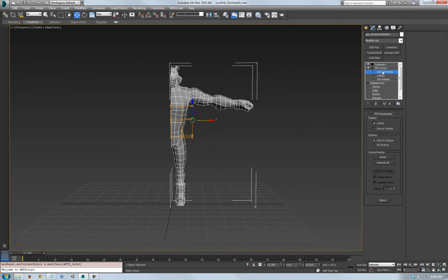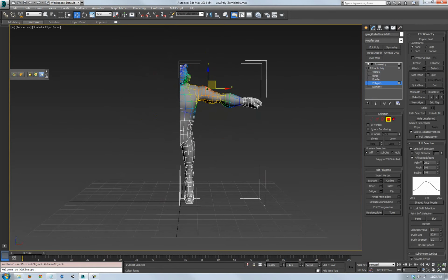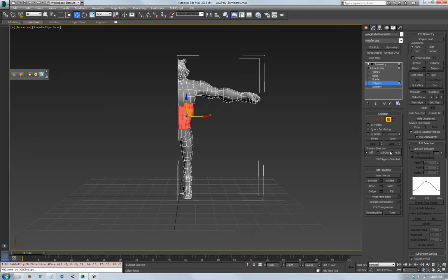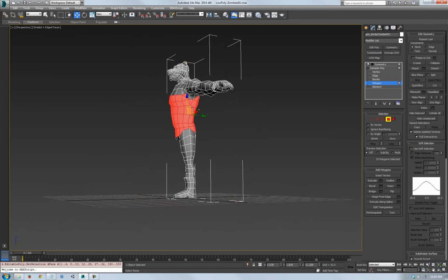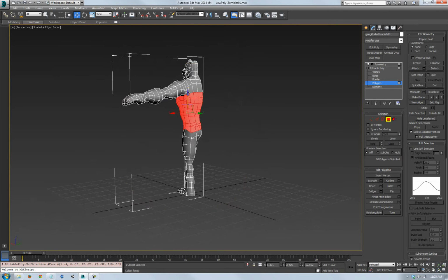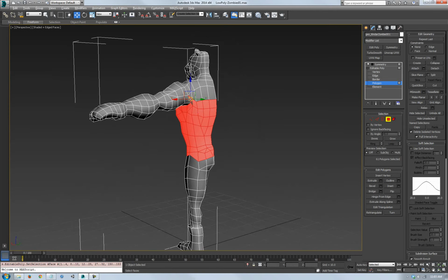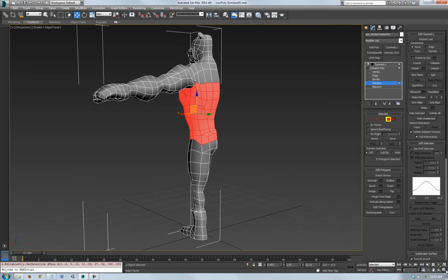Alright, so say that I've got this volume here, and when I go into the control points to modify it, as you can see, when I move this around, it's also moving the rest of the mesh around. So this does have a lot of potential power in it, but it also has its limitations if you're just using it straight on top. So instead of that, let's get rid of that, and for the polygons that I want to adjust, let's select them. Let's add these up here, and let's grab that one, let's grab this one. That should get me good enough results.